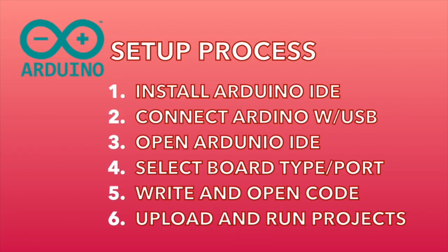You can start with simple programs like Blink or Serial Print. Finally, click the Upload button to send the code to the Arduino board. Once uploaded, the program will automatically run on the device.